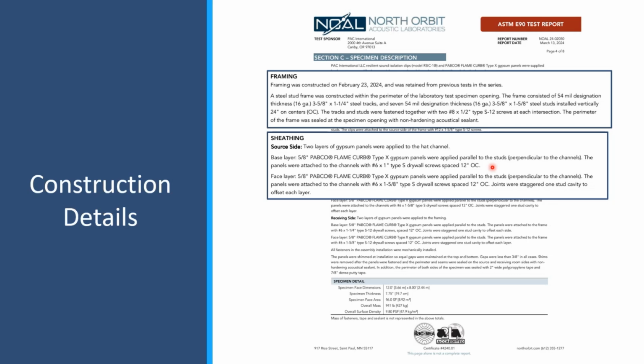Typically, wider screw spacing will get better acoustical results. Tighter screw spacing will get lower acoustical results in those assemblies where screw spacing affects things. Screw spacing is also dictated in UL fire designs. So if you have a UL fire design that requires a maximum 12-inch on center screw spacing, but you've got an acoustical test with 16-inch on center screw spacing, that acoustical test isn't entirely representative of what you're actually going to get in the field.